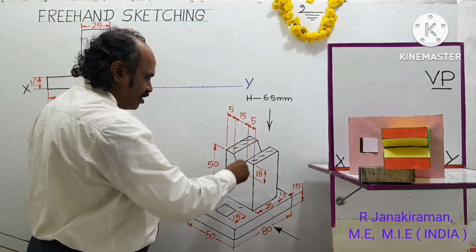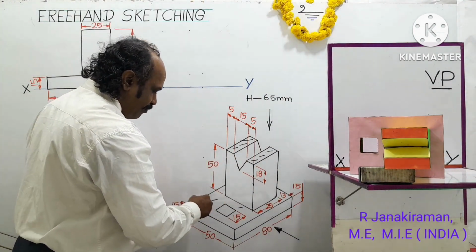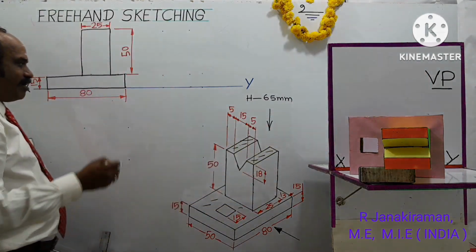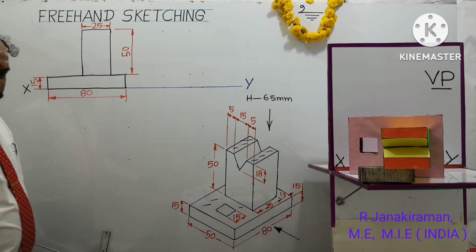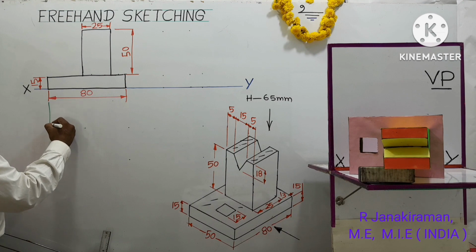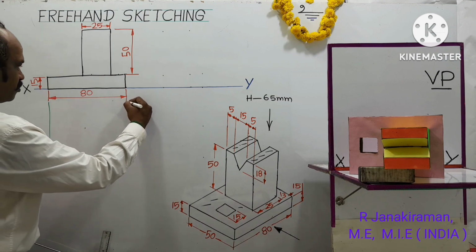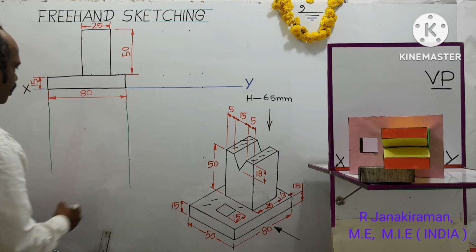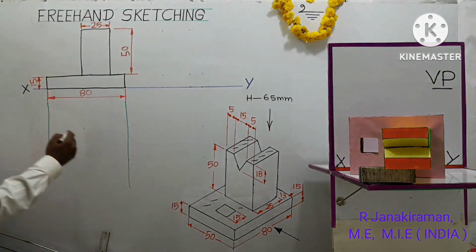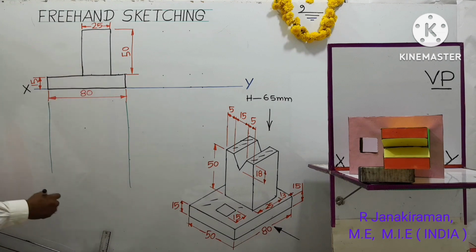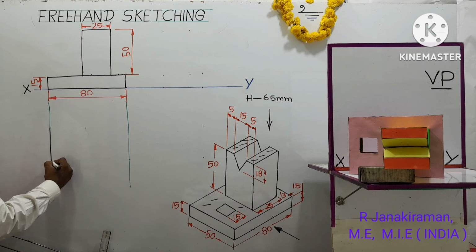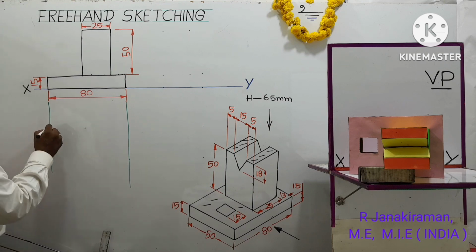The portions visible are already explained, and you can see the breadth of the object, and you can see the length of the object. Length of the object will be the same as the front view length. So you project from the previous front view, draw a vertical projector using a 2H pencil. Okay. Now the breadth is given as 50 mm. 50 mm breadth means somewhere below this diagram, you can take your own gap, and draw a horizontal line.